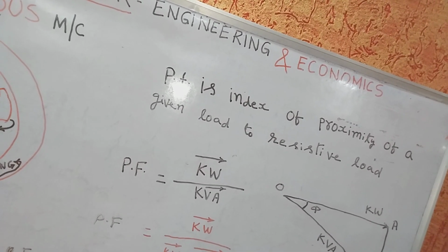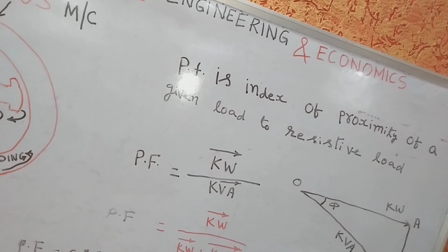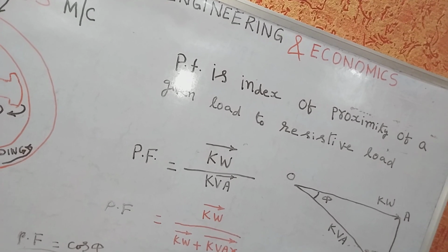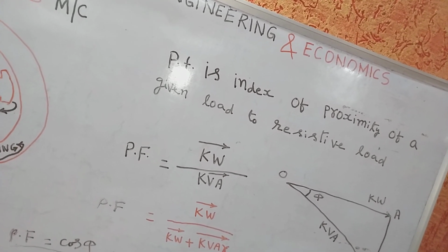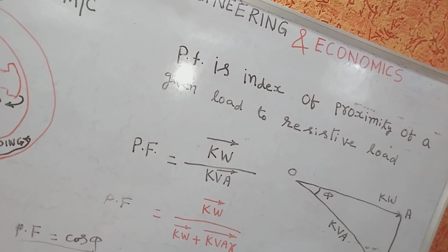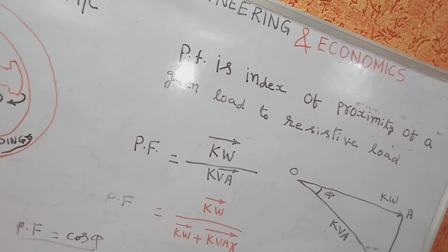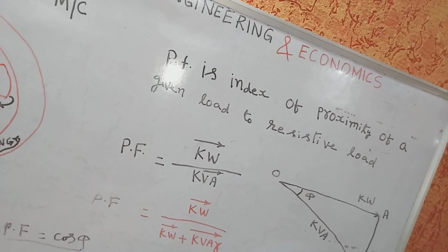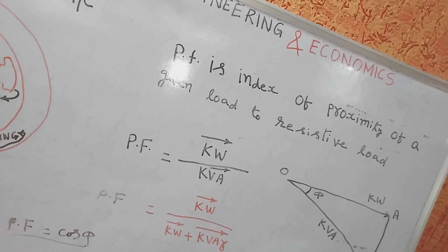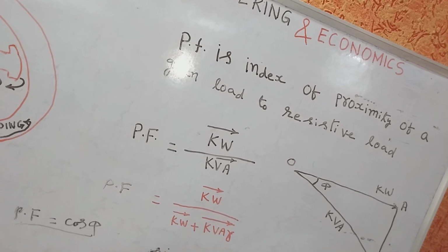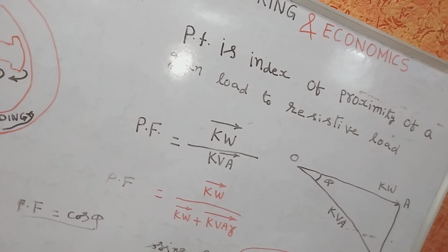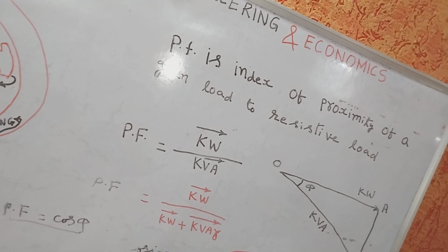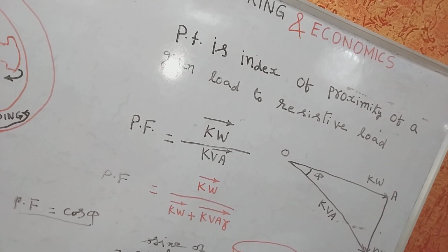Secondly, low power factor means more current and greater copper loss in generating and transmitting equipment. The third disadvantage is poor voltage regulation. Factors influencing reactive kVA requirements in motors are visualized readily in terms of the relationship of these requirements to the establishment of magnetic flux.